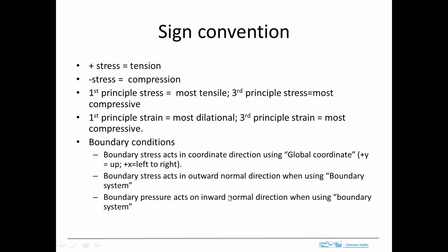Okay, so you can go back and refer to these if it would be helpful. But one thing to keep in mind is that this is kind of confusing. You can have these different ways to specify boundary stresses, and I think the upshot is that as you're getting used to this, you just need to set the boundary condition up, run the model, and check and verify that it's acting in the right direction.